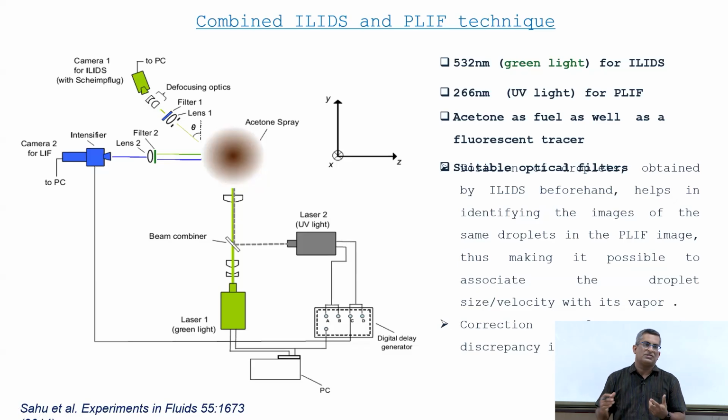For instance, in case of an evaporating spray, let's say you have a fuel spray, you inject a fuel spray, the droplets evaporate. And now how does the carrier phase composition change? Why should it change? Because you are adding vapor to the surrounding phase, to air, let's say, in combustion applications. So now you have a mixture of air and the fuel vapor.